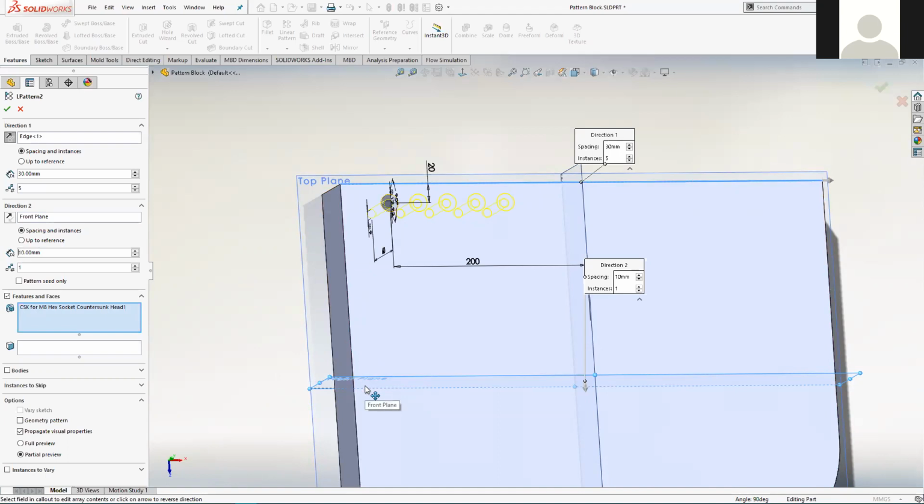Again, it may seem logical that you would think, well, that plane runs left to right, so aren't you just selecting the same direction reference as that top edge? And logically, I agree, that might be a sensible interpretation, but that isn't how it interprets it. It interprets it as meaning normal to the plane, so that's at 90 degrees to the plane.